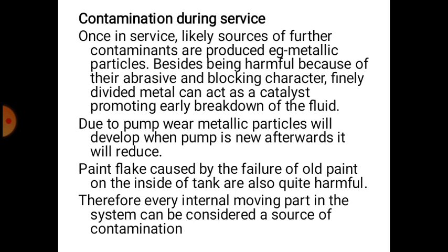Contamination during service. Once in service, likely sources of further contamination are produced, for example metallic particles. Besides being harmful because of their abrasive and blocking characteristics, finely divided metal can act as a catalyst, promoting early breakdown of the fluid. Metallic particles are very likely to be developed in a new system due to initial pump wear. After a suitable running-in period sets in, the wear rate of pumps and other mating parts gets reduced due to the lubricating property of the fluid.